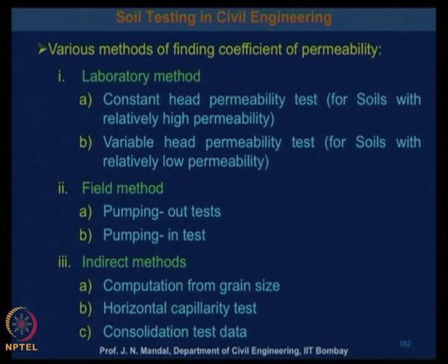There are also field tests, the pumping out test and pumping in test, so you can directly determine the coefficient of permeability of the soil from the field.